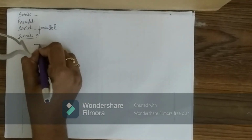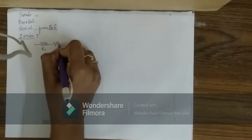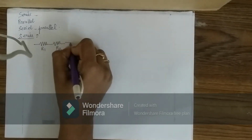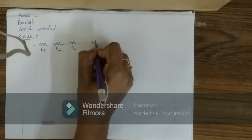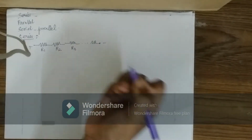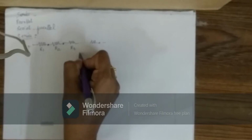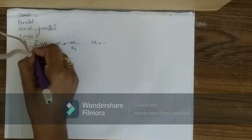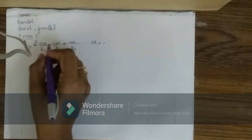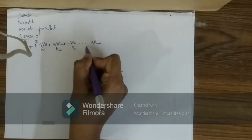So for example, R1 is connected, the other end is connected to R2 and R3, etc. up to Rn. So this is called a series connection, series circuit. Here the same current circulates through every resistor. Let's take the current as I. So this current I flows through every resistor.